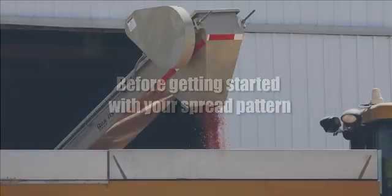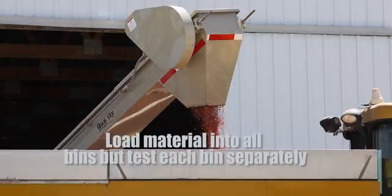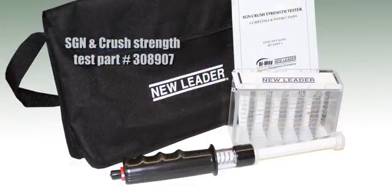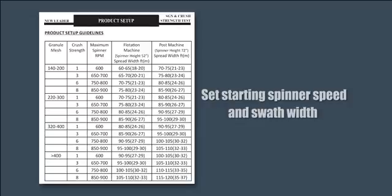What you need to do before getting started with your spread pattern. Load material into all bins, but be sure to test each bin separately. Set and verify your feed gate height. Test your product using the SGN and Crush Strength Test Kit, part number 308907. Now set your starting spinner speed and swath width using the chart provided.